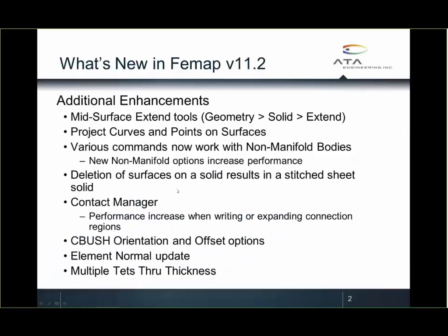So there are a few other enhancements that they included in 11.2 that I don't really have time to demo. They added some mid-surface extend tools. When you're mid-surfacing a solid model, a lot of times you have small gaps between your mid-surfaces where they're not connecting. They've added tools where you can extend those surfaces to other surfaces. This is very convenient when you're mid-surfacing.